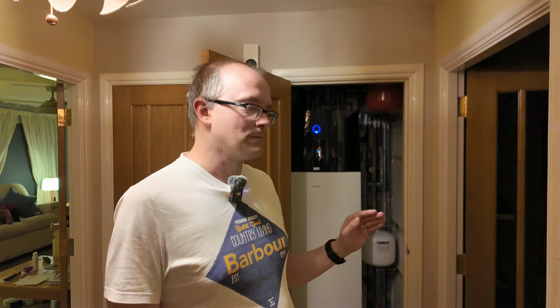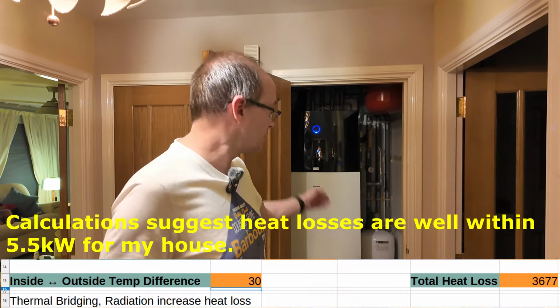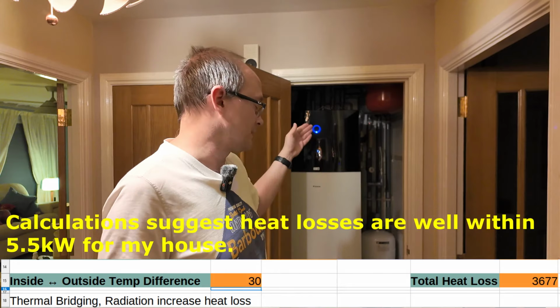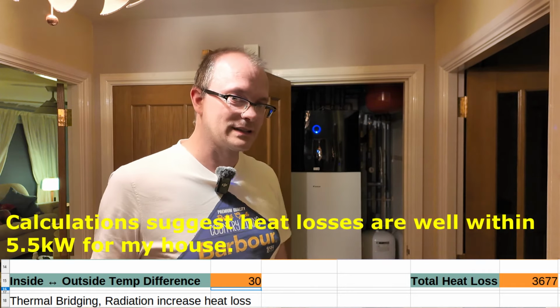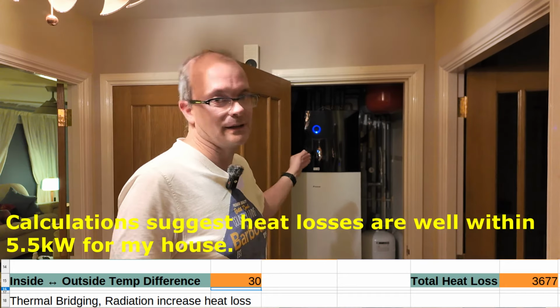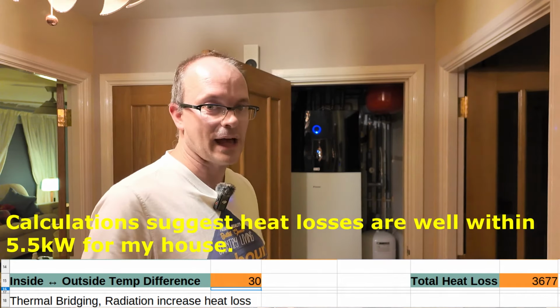kilowatts. If we look at the data sheets at a temperature of -7 degrees, you've got a coefficient of performance of about 1.9. So at -10 degrees Celsius, your maximum output from your compressor only situation is going to be about 5.5 kilowatts. So if you need a heat output which is more than 5.5 kilowatts, you're going to need to use the backup heaters. So that's very interesting. You look at the data sheets, it says it's rated at 8 kilowatts at -10 degrees Celsius, but that's with the backup heater. On its own, it cannot achieve that 8 kilowatt output at -10.